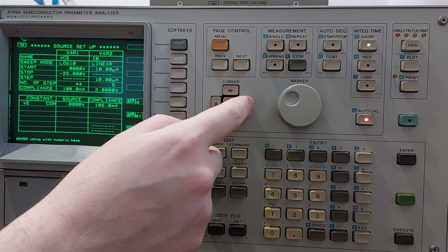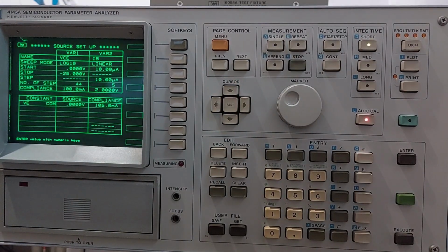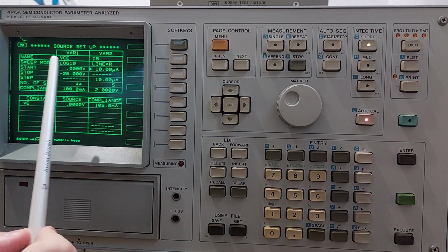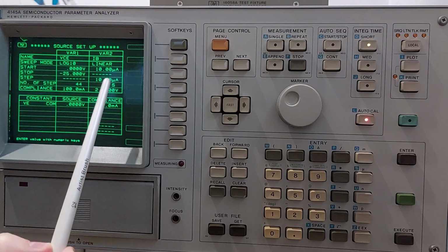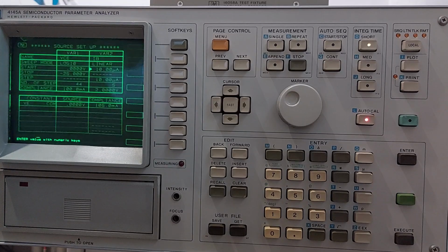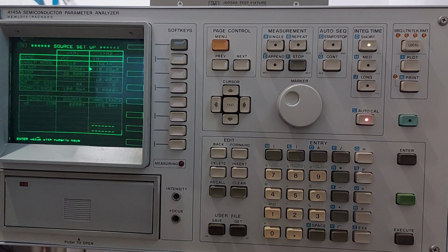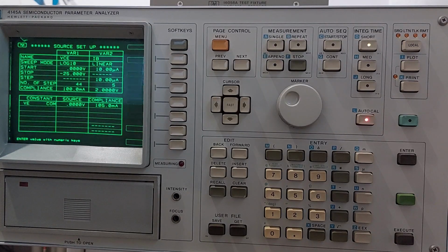Then we will move to the base current settings, and for this usually 5 values is enough, so the SMU will just switch the base current 5 times. So for such transistor the base current usually is 1% of the collector current. So if we know that our collector current is 100 milliamp, the base current should be around 1 milliampere.